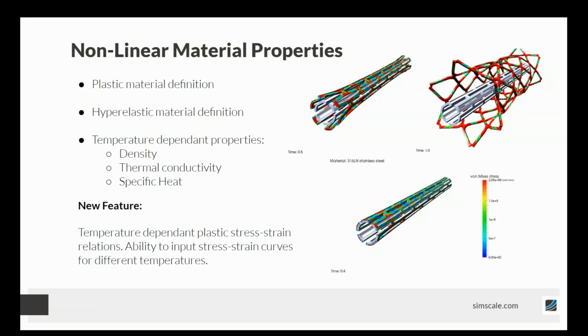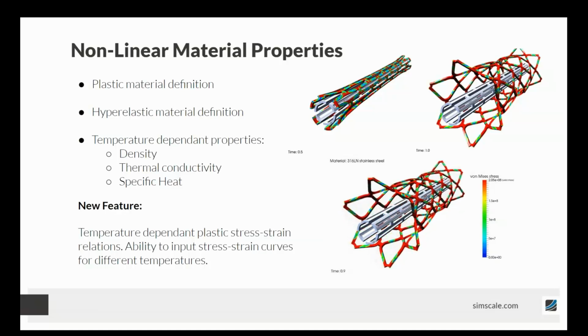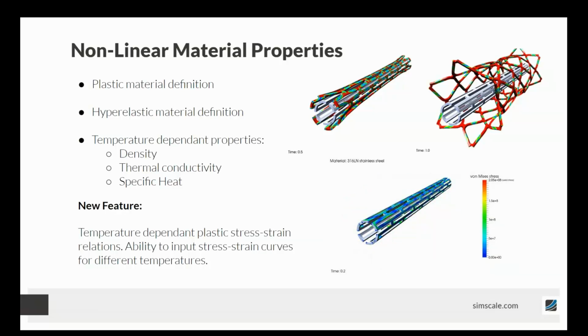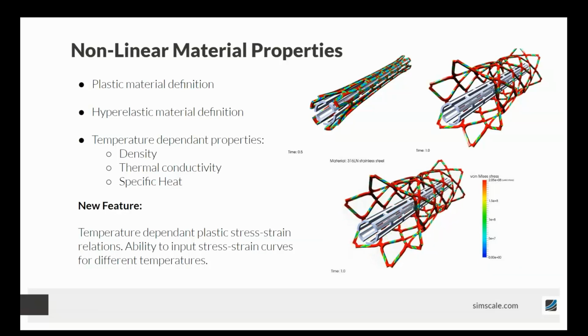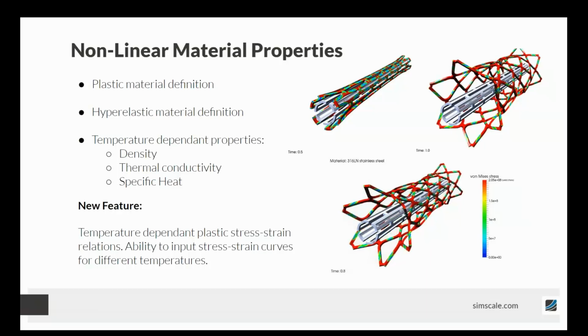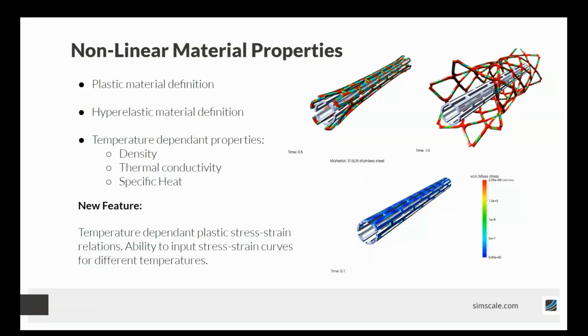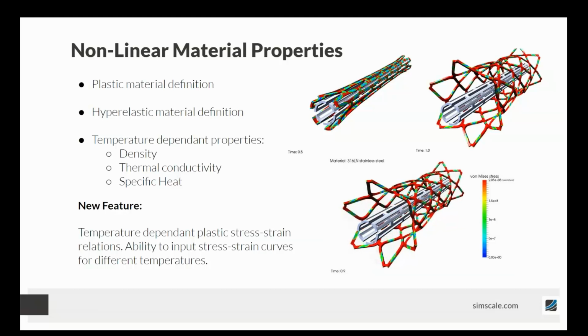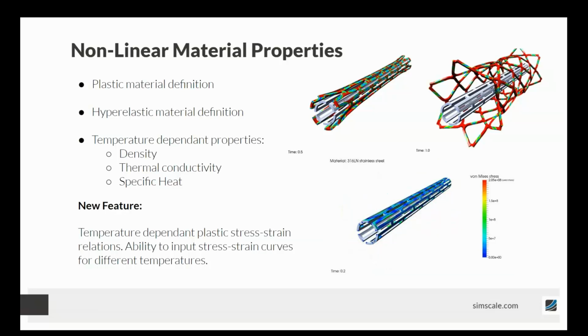Now what I really want to highlight today is the fact that we have now implemented temperature-dependent plastic stress-strain relationships, which means that we can essentially upload multiple stress-strain curves for the different temperatures that are going to be seen during the simulation. So as a component heats up, the stress-strain relationship is actually going to depend on that temperature. And so we'll get into that a little bit more in just a moment.